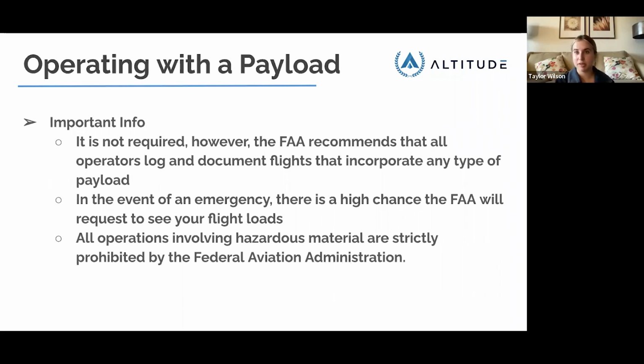But just so that it makes sense, I'm going to give you guys a few other definitions that also tie into that. So we have our basic empty weight, which refers to an aircraft's weight to include unusable fuel and oil before you're adding passengers and usable fuel. Then we have our useful load, and our useful load is now the amount of weight we have available to add fuel, passengers, cargo, and all that fun stuff, given the limitations of the aircraft. Now, the payload is basically the useful load just without the usable fuel. So what we're concerned about here with the payload is the weight of occupants, cargo, and baggage.